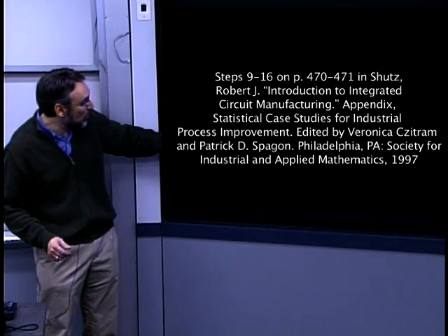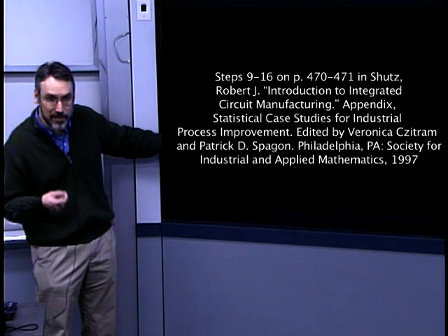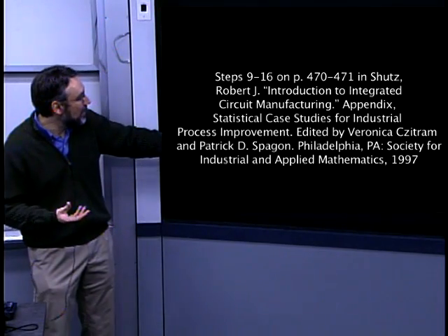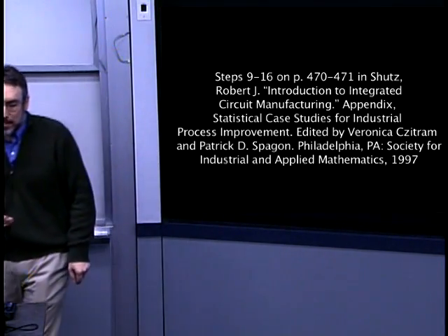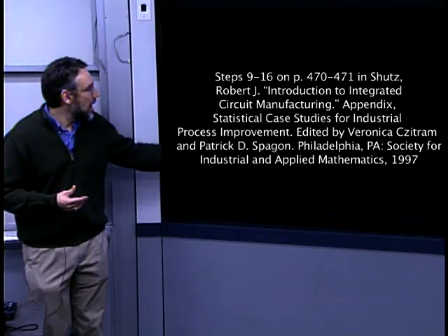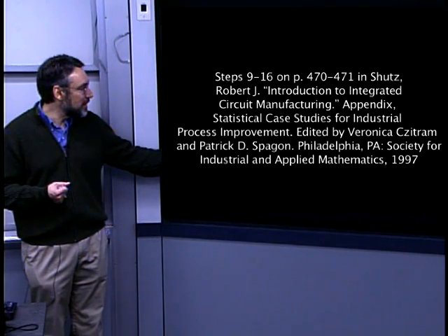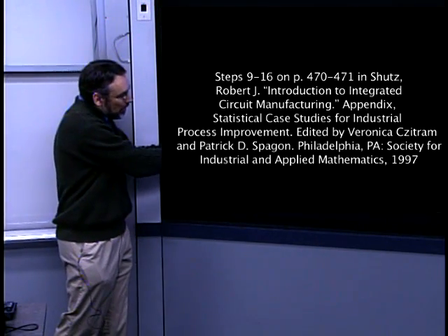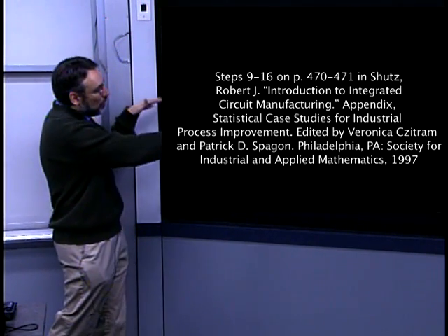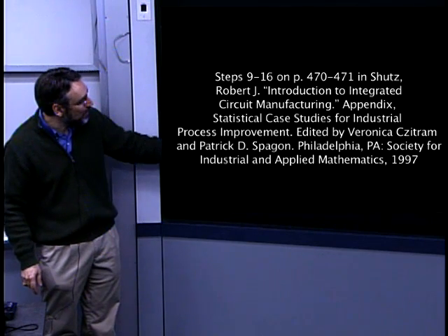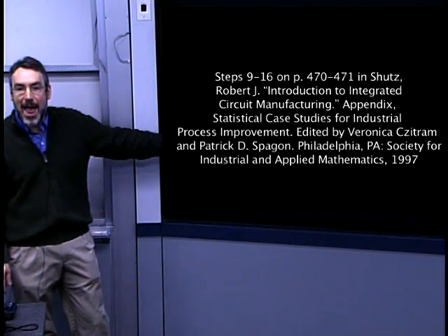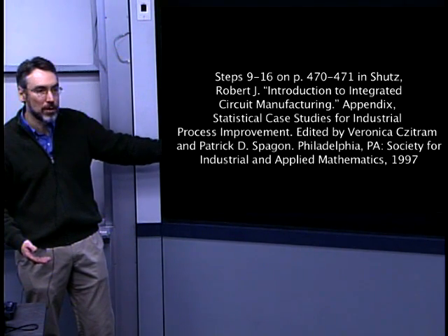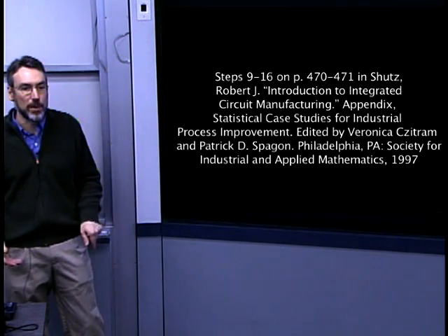Those regions we don't want to dope underneath the channel. We want to keep that fairly lightly doped so that we can invert it for electrical action. And in this case, we're getting something often referred to as a self-aligned process whereby we don't have to selectively shoot the ions just in here. We can blanket the whole wafer and use these thick oxide and use the polysilicon as the mask itself to prevent the ions from reaching the underlying silicon regions.